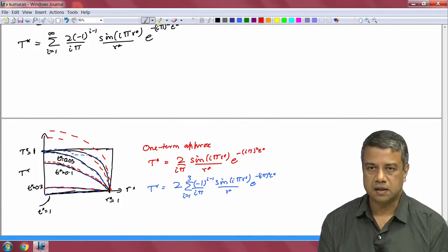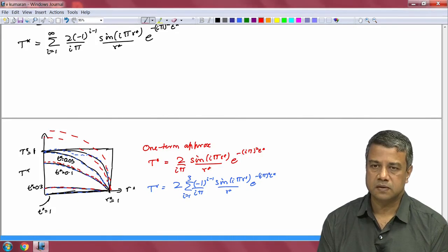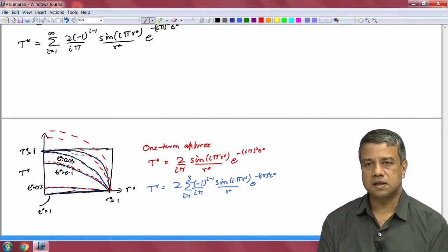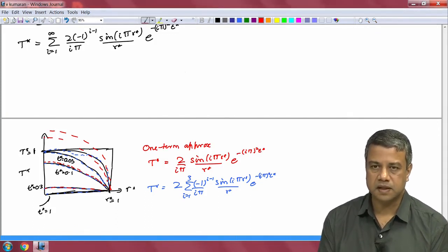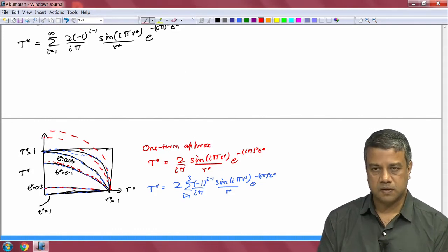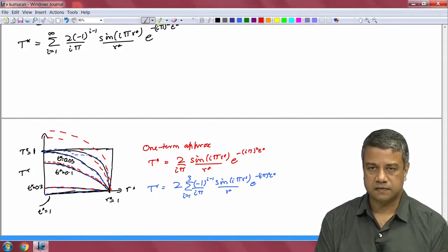Greater than that it is not quite accurate. The similarity solution is valid so long as the thickness is small compared to the radius, so that you can consider it to be conduction from an infinite plane surface.